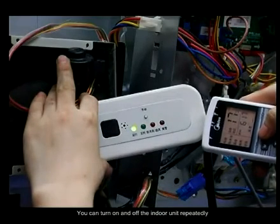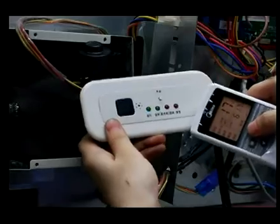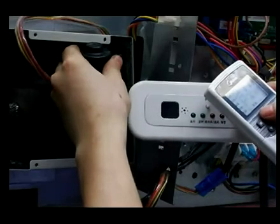You can turn the indoor unit on and off repeatedly and feel the action of the throttle part and the refrigerant flow by hand. If this doesn't solve the malfunction, you need to replace the valve and clean the system.